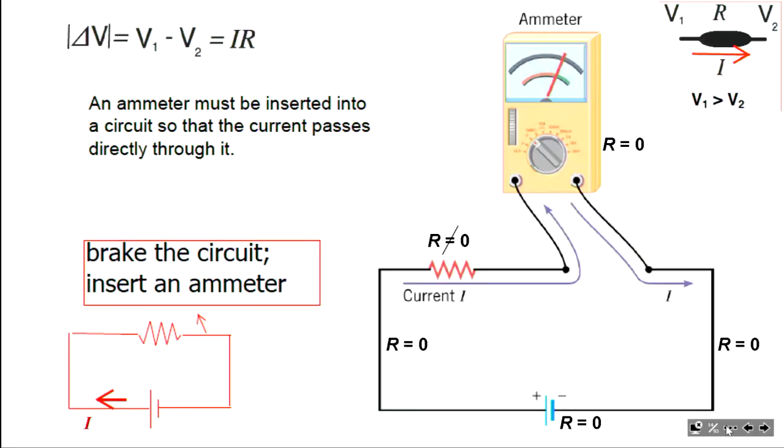We call them DC and AC, and DC means direct current. Direct current means it's constant in time, and that is happening when we use the battery. AC means alternating current. Alternating voltage is what we use in the power outlet. It changes in time. So we have to use settings accordingly. If we use a battery, we have to use a DC setting, direct current.